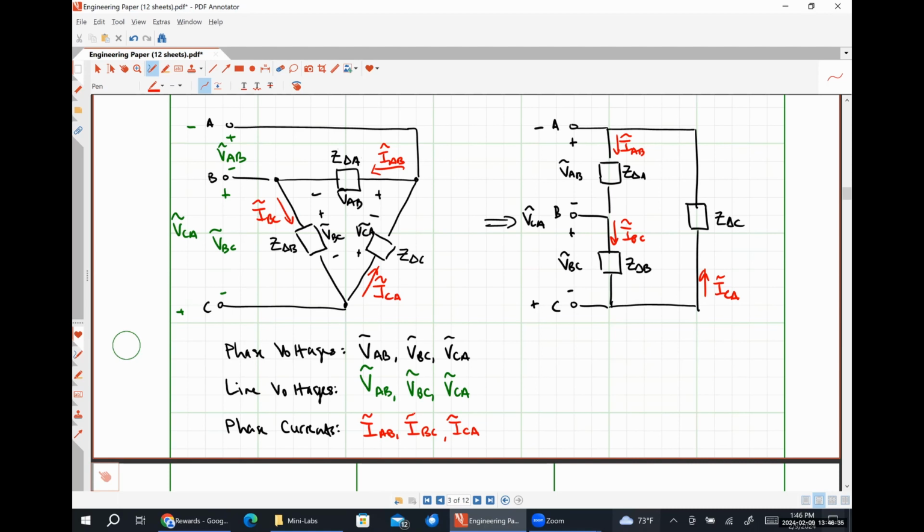However, the capacitors also have to be rated for a larger voltage in a delta configuration. So we're going to see, once we start doing our analysis, that the voltages, like our line voltages and our phase voltages, are going to be proportional to each other by specific ratios. And those ratios are going to help us figure out how to connect impedances for different applications. So there's really not a hard and fast rule. It's application specific.